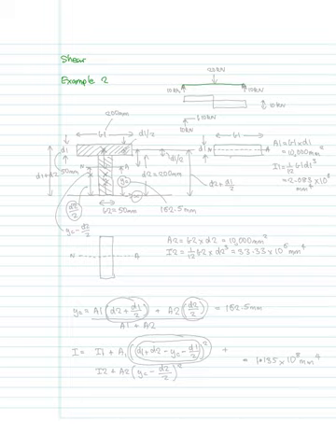So presumably there would be a beam like there of some form with a load coming down of 20 kilonewtons, and then the shear force diagram would be 10 kilonewtons on each side, because the reaction on each side would be 10 kilonewtons.